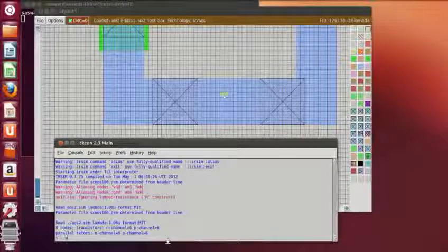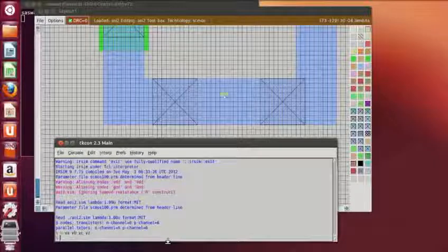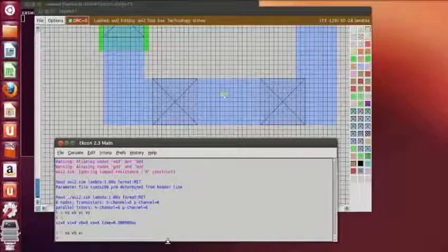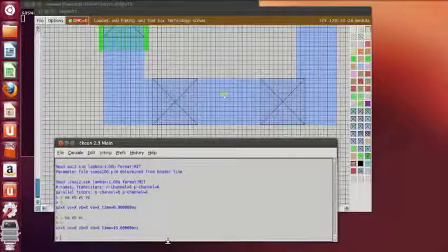W for watch, VA, VB, VC and VZ, the three inputs and the output. Then D for display, so we'll get XXX, that is the default value. Now if I type low VA, VB, VC, then type S for step, then the output will be 1, obviously, since AND of 0 0 is 0, OR of 0 0 is 0, so the invert will be 1.